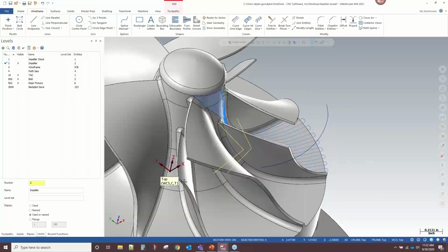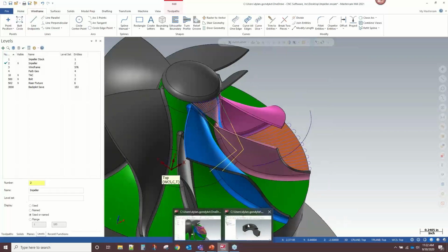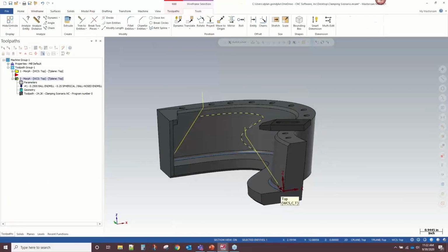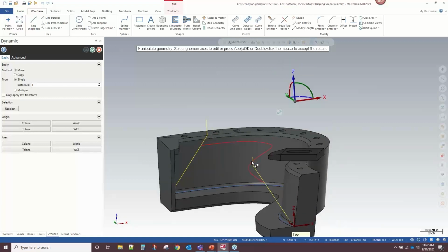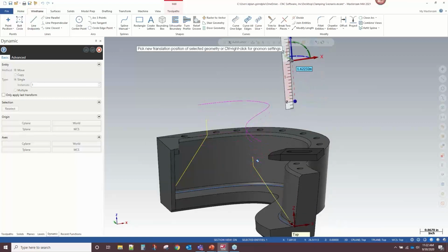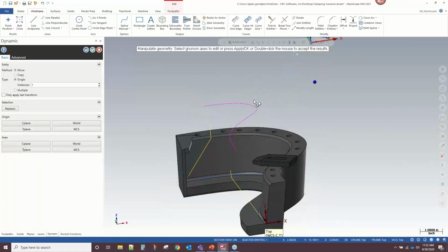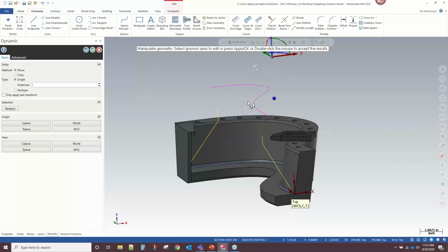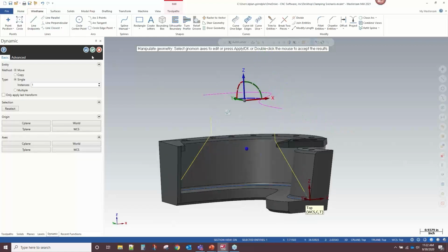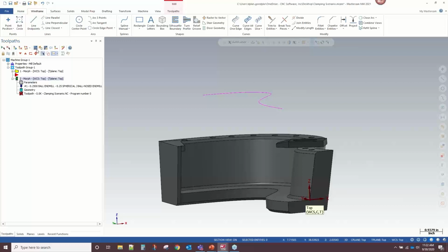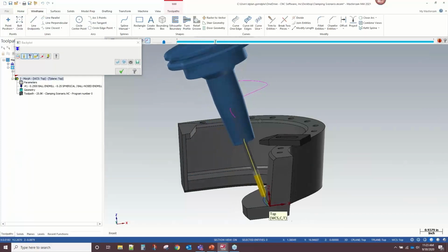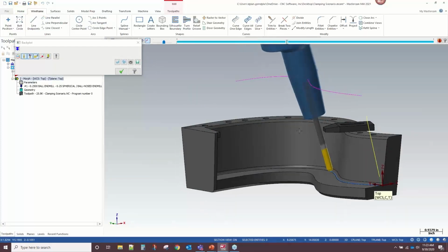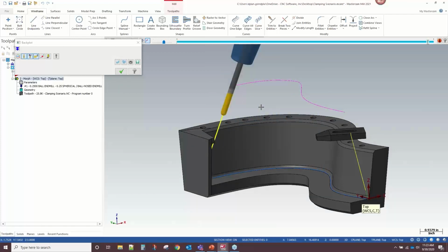Yeah, so that is based upon what you want your tilt to look like. So if we go back to the last example for a second, if we raised up this spline, and remember that our toolpath is now tied to this geometry, if we change the geometry, the toolpath will go dirty and we'll regenerate it and the motion will change. So if we just raised it approximately, that was probably a 2-inch rise, it changes the angle the tool has to point through. So in this case, I'm actually still avoiding that clamp, but the tool is remaining much more vertical.